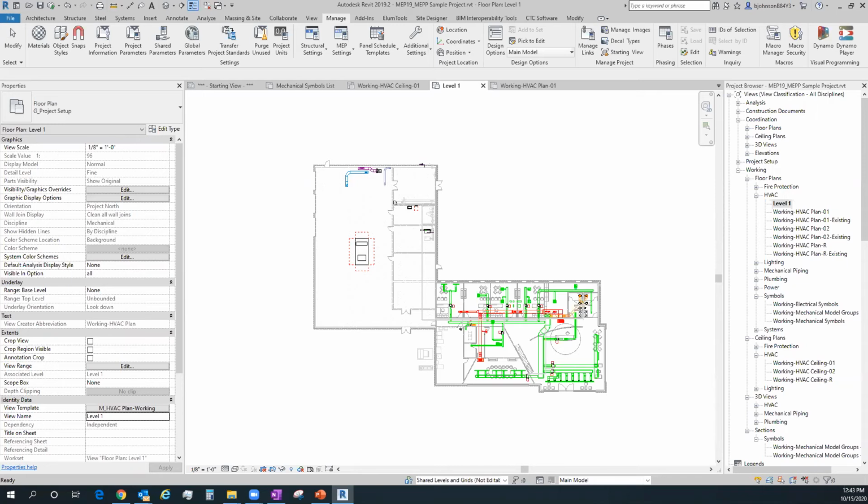Another cause is not everybody being on the same Revit version or hotfix. If you're in a larger firm, sometimes hotfixes are deployed through something like SCCM, or through a batch script or a robocopy, to get the change out. And typically when those happen, not every machine is potentially turned on. Somebody's out on vacation for a couple of weeks, they took their computer home with them and they're not within the network, so you can't drive that session to do the update. So it depends on IT's capabilities to track hotfixes and updates: are they actually deployed correctly on every machine or not?